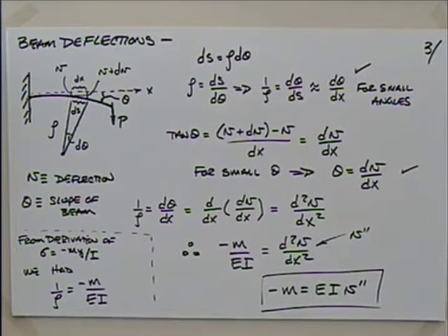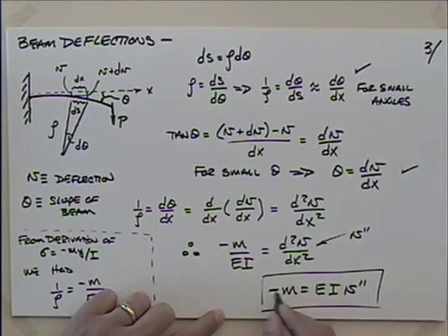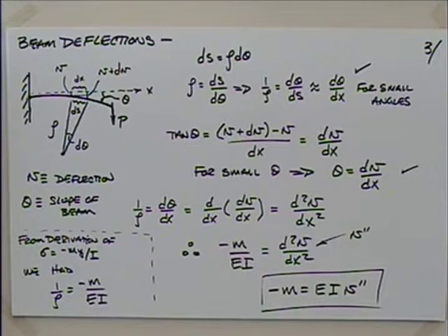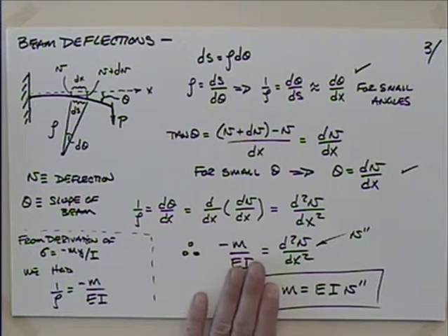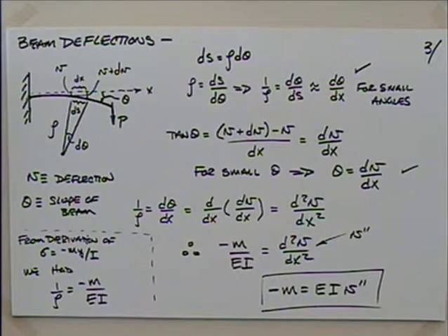Okay. Now, if you go through your author, your textbook doesn't have that negative sign there. I take deflection positive down because most of our beams deflect down. Your author takes it as positive up. Just a little bit of a difference there. But whether you have that negative sign or not, the equation still holds, and the process we'll go through